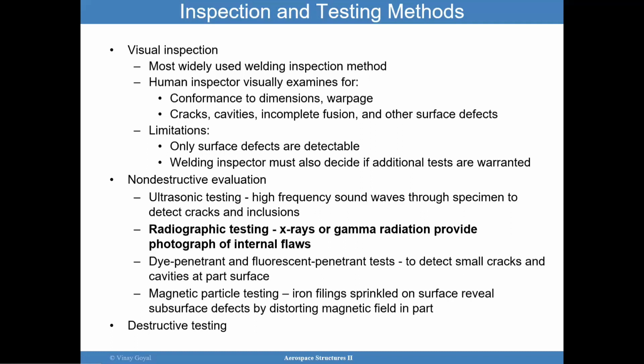Non-destructive evaluation is really nice. It provides a view of what's going on inside in the areas where you cannot see, and ultrasonic testing is one way to accomplish that. You send high-frequency sound waves through the specimens to detect cracks and inclusions. You have radiographic testing, X-rays for example. Dye penetrant can be very useful and can detect small cracks and cavities. And then you have magnetic particle inspection, which can help reveal subsurface defects by distorting the magnetic field.